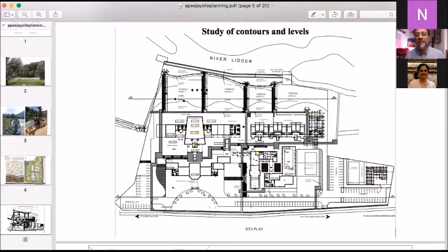So very clearly, the topography was taken care of first. Secondly, the climate, which dictated a lot of rain and snowfall, so we created that canal in between to take care of the surface drainage. And then the project program led to this concept that we distributed the functions into 4. And because this was a fairly large site, we had to look at ways of execution.